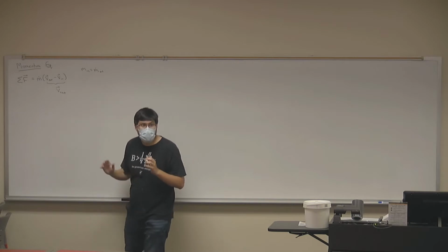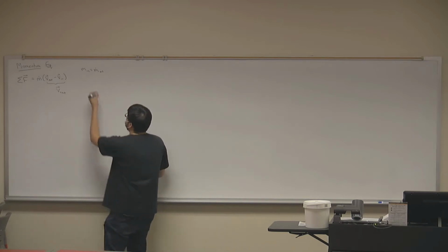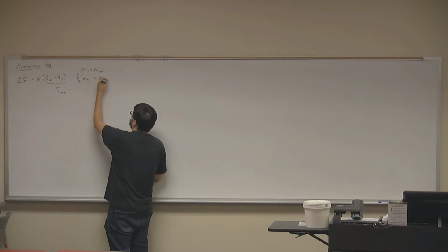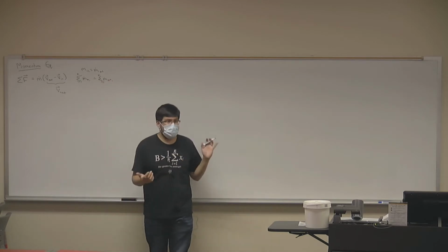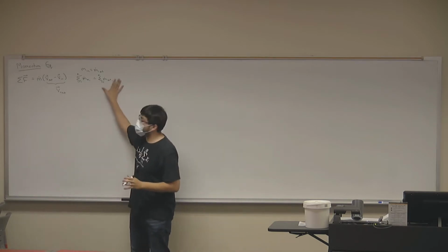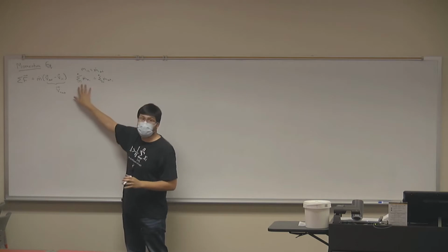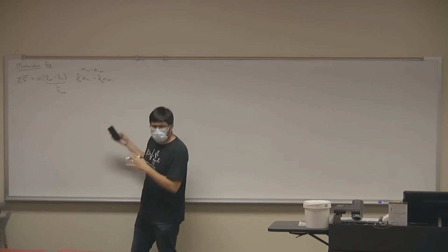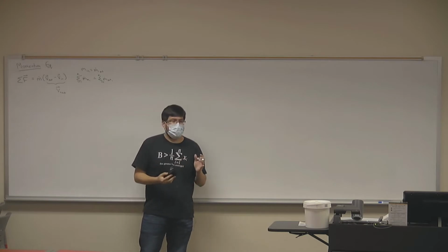So what matters from a continuity standpoint is that your mass flux ins equal your mass flux out, however many they may be. In other words, if you have two outlets, then the sum of those two outlets should equal that one inlet, and vice versa.